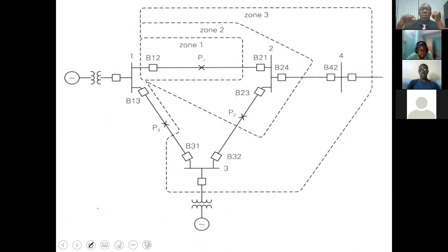All right? Now, the problem is, if that wasn't the case, if I was just looking at impedance magnitude and had it looking in both directions, the question is, it could operate for a fault behind. So we do have a directional element applied to your distance relay. So they are all looking in front, right? They are not concerned with what's happening behind. Of course, later on, you'll see that we have a setting that looks behind, in terms of the whole operation.